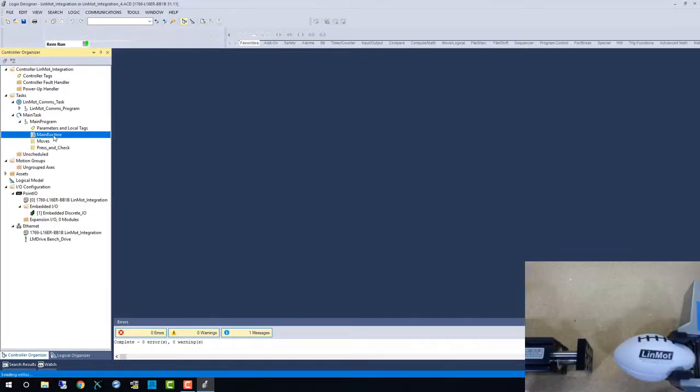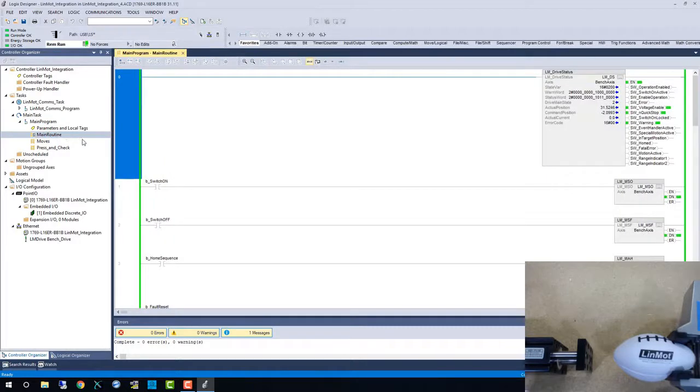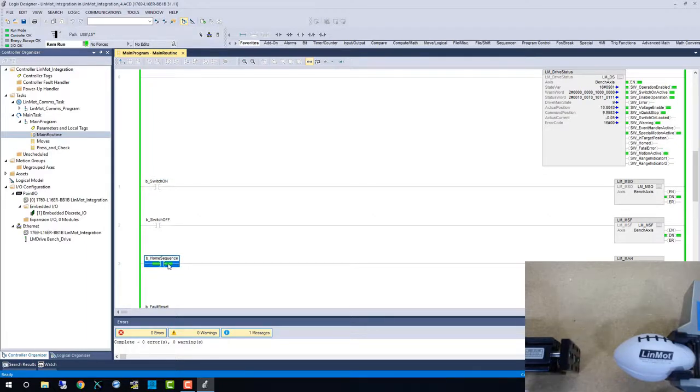In the bottom right corner you will see the test rig. We have the LinMot motor opposing a LinMot football being held in a tabletop vise. The goal is to simulate wear on this foam football by applying a 22 Newton press or about 5 pounds of force.